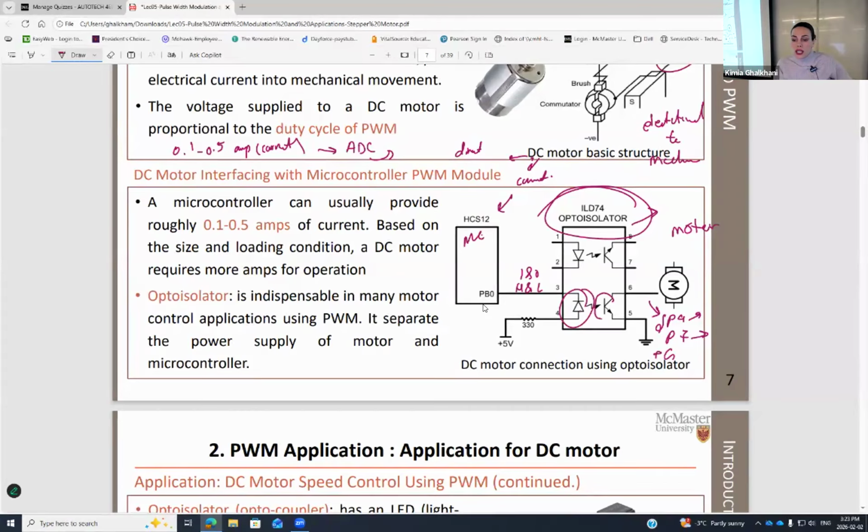I do have another switching sensor. This is just a switch, and what it does is close the circuit. Each time you generate high, the switch closes the circuit and sends it to the motor, right from here to here. Next time it switches to 0: first this one is set to 0, the switch opens, and then 0 is sent to the motor. That's how you can create the pulse width modulation through an opto-isolator. So far, makes sense, kids? Everyone got the point? I think it's time to give you a break, and then I'll continue after the break.